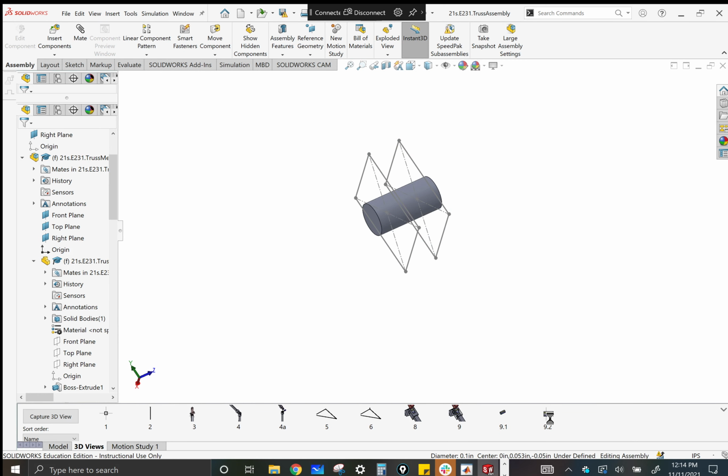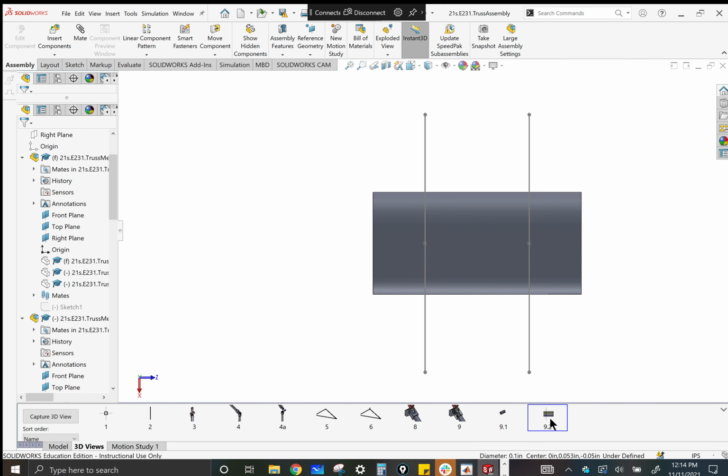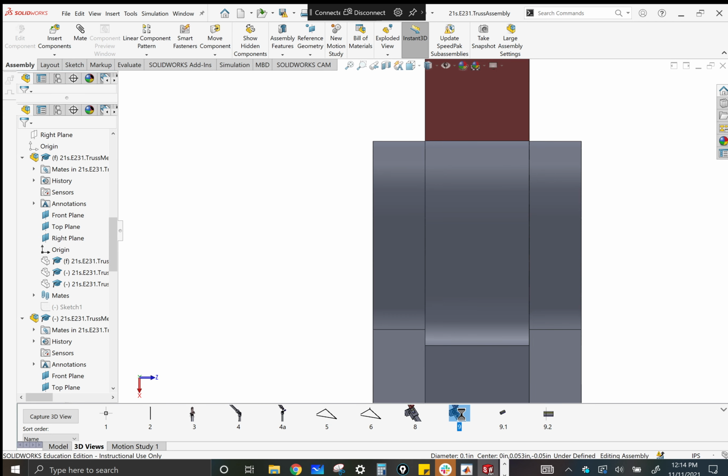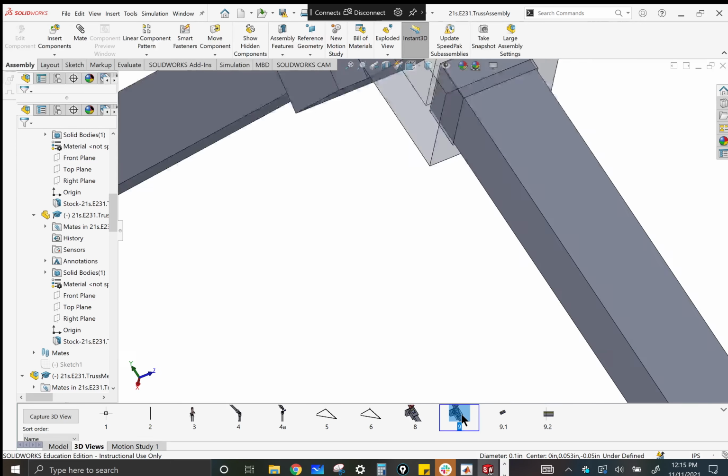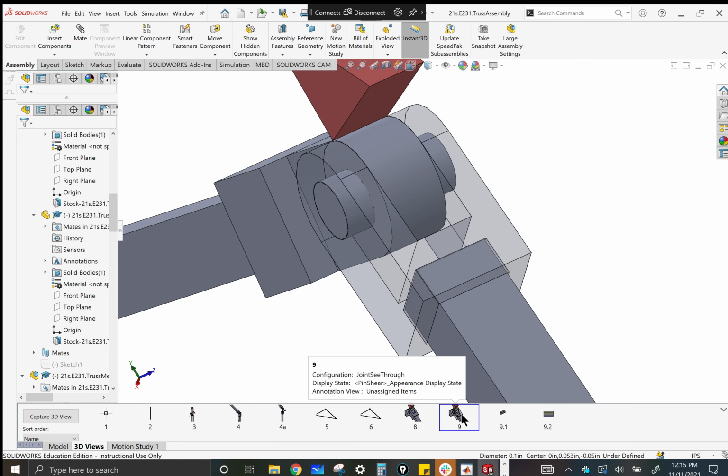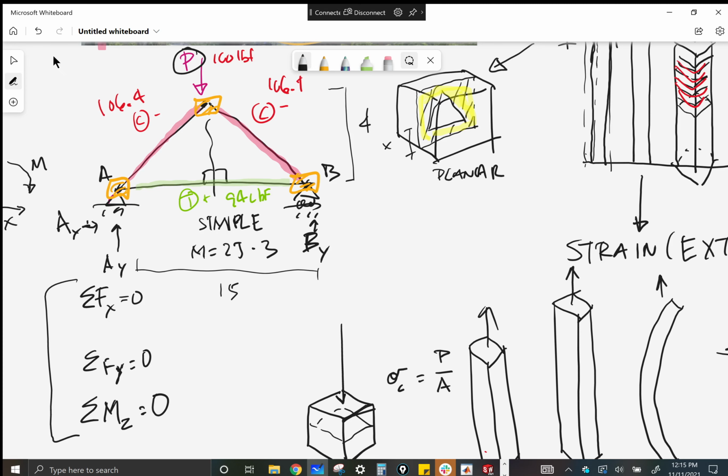There are 2 cross sections that the load is taking, here and here. And the idea is that the load goes to the pin first and then is transferred through the centroid. That's another basic thing I didn't say about simple planar truss theory. The loads are considered to only arrive at the joints, okay?